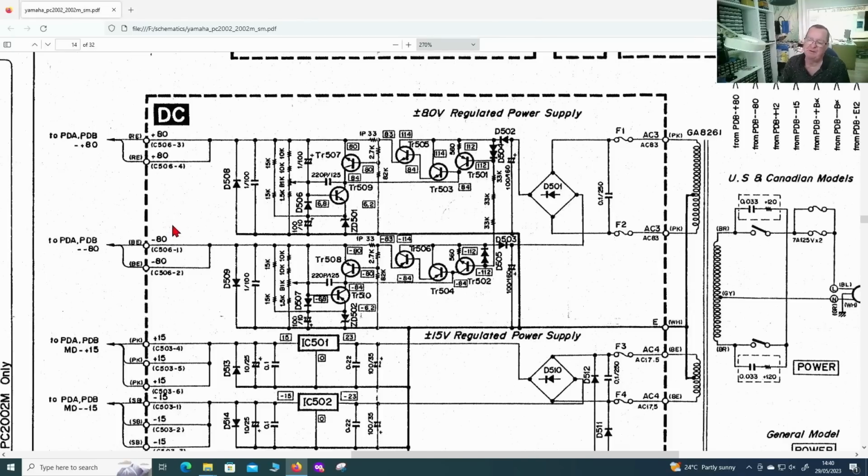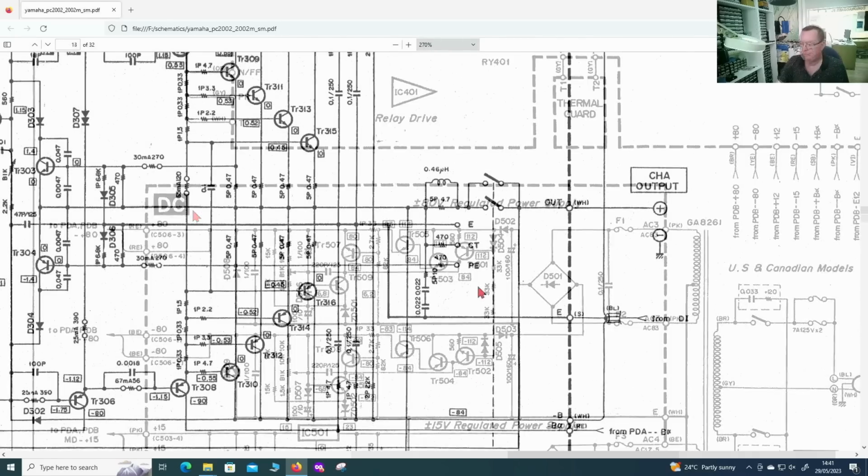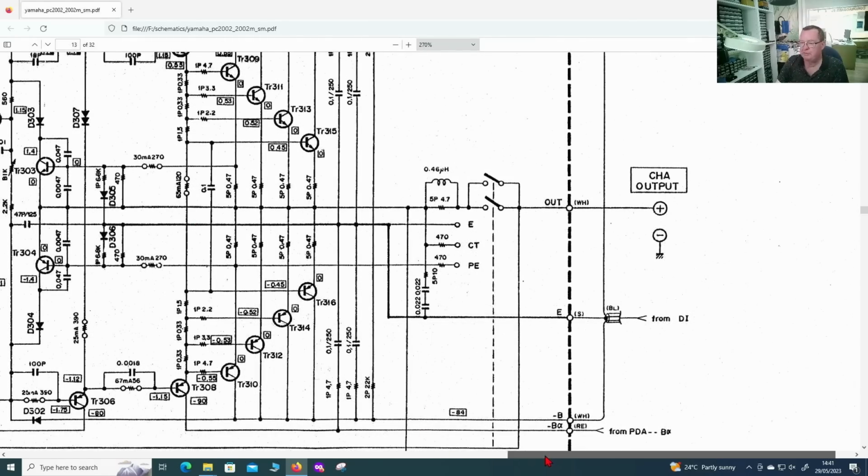So basically, one of two things is going to happen. Either A, whatever is the 80 ohms here is going to burn up because it can't handle 80 watts. Or two, this power supply is going to shut down because it can't supply 1 amp. In our case, the power supply is shutting down. There's no plus 80 on either amplifier, and this is why we have the protect mode. What do all these voltages do?